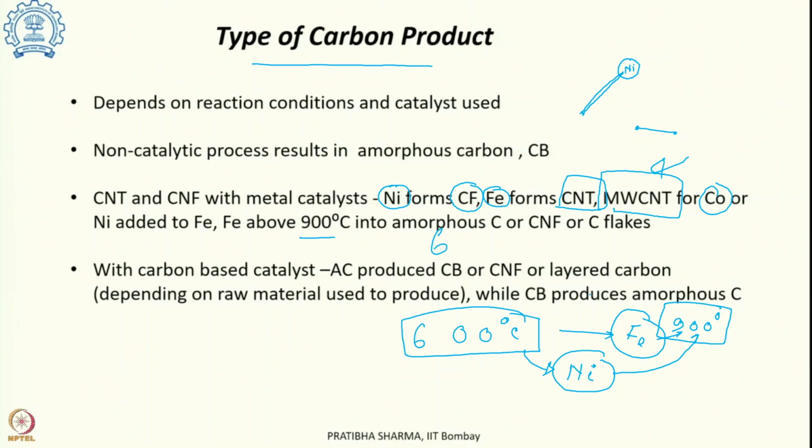Yes, according to the temperature we decide which catalyst will be used, because at higher temperature nickel will not be stable. Nickel has very good activity, meaning very large active sites, and its conversion rate is very high. Conversion rate means hydrogen production from methane is very good, but we will not use it when the temperature is above 900 degrees centigrade.